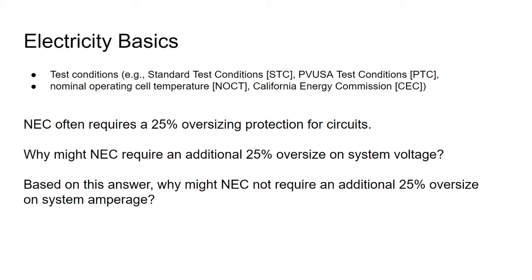Solar, its voltage and amperage ratings are given at a test condition that is not reflective of their field performance. That 60 degree Fahrenheit to 77 degree rooftop temperature day is not reflective of the system on a sunny winter day when it's 15 degrees outside, not 60. Or a hot summer day when it's 160 degrees up on the rooftop instead of 77 degrees in the laboratory environment.